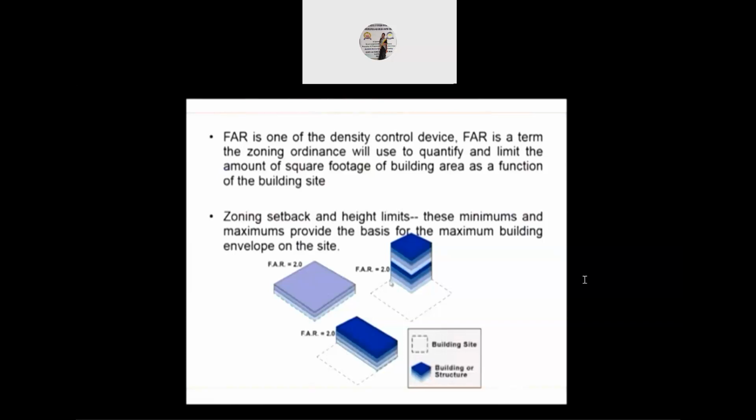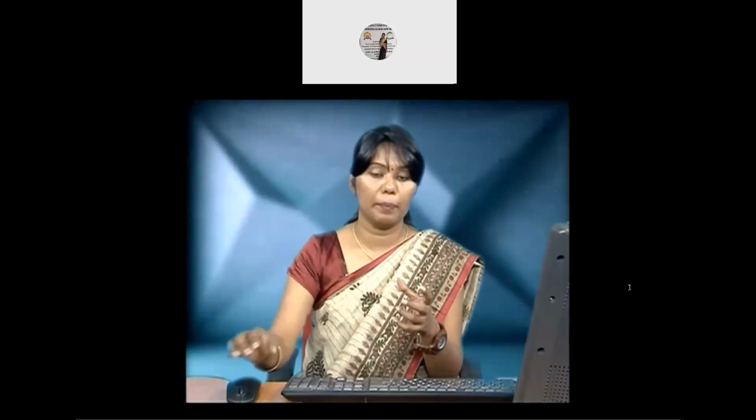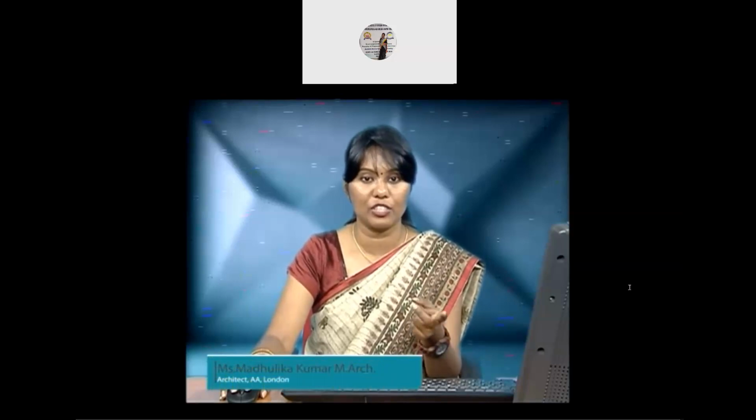And there is one more option in which we can divide the whole site into four parts and only one fourth of the whole plot is being used for construction and everything is being stacked up on top of each other, which creates almost eight floors, and we have almost three-fourths of the entire plot as empty. So all these methods are right. Even though we might not be able to choose, we might streamline depending on the height restriction and zoning patterns that is being used on the site.